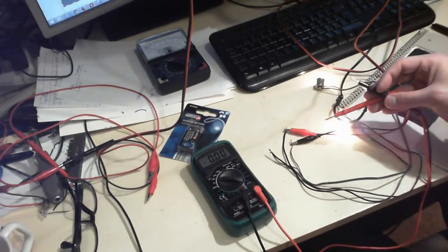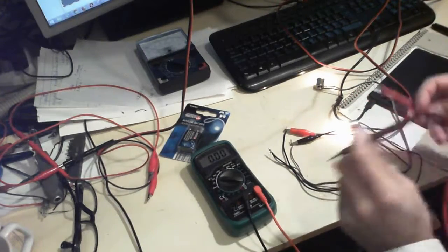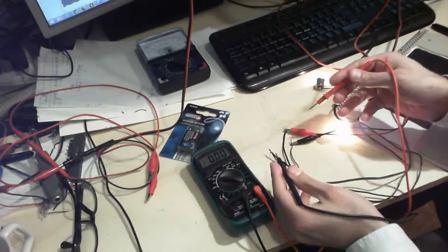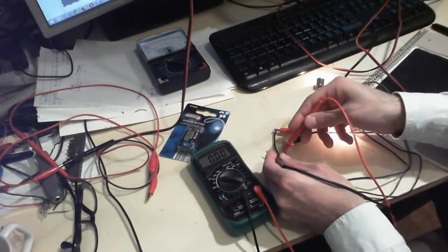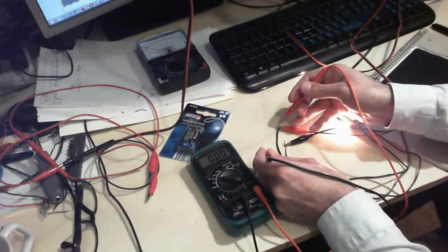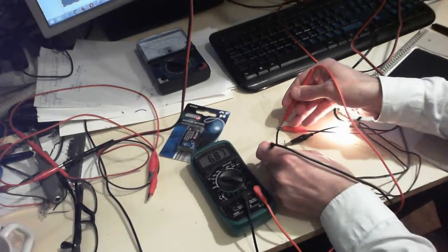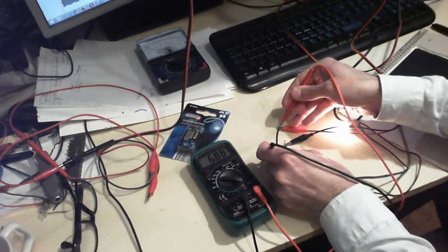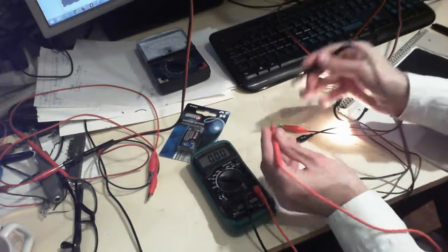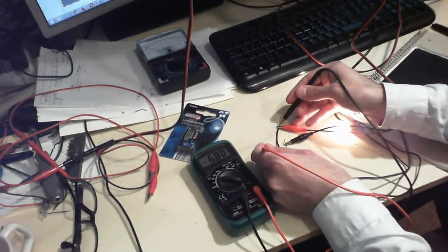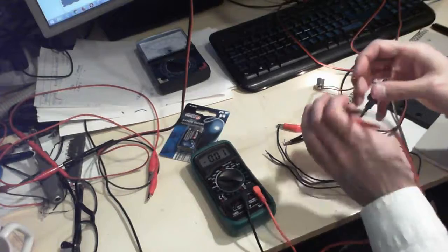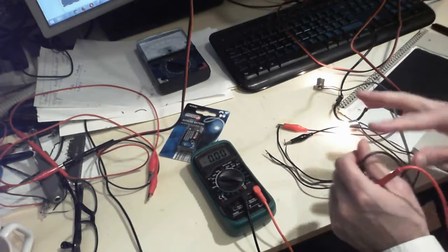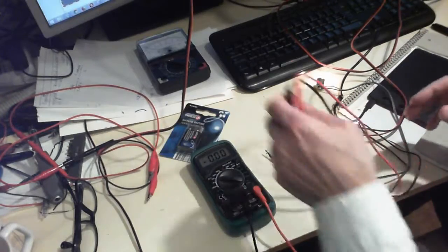Now the voltage drop that you see on these two lamps is also the same story. The voltage drop across, for example, these two wires together is going to make one lamp. If I set my multimeter over here like this, I'm going to get 6.88 volts, which is a positive reading. Now if I reverse the order and probe the voltage like this, I'm reading negative 6.8 volts. So that's basically the voltage drop polarity in a circuit.